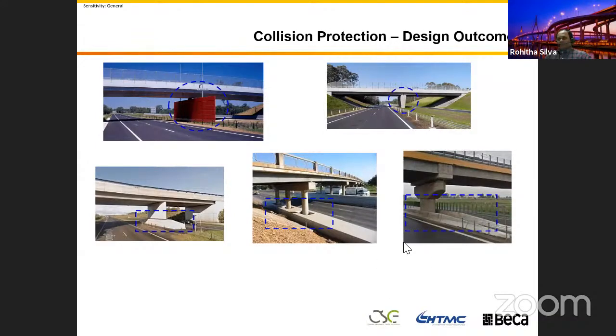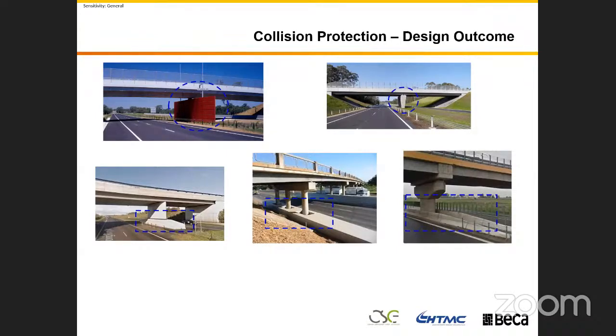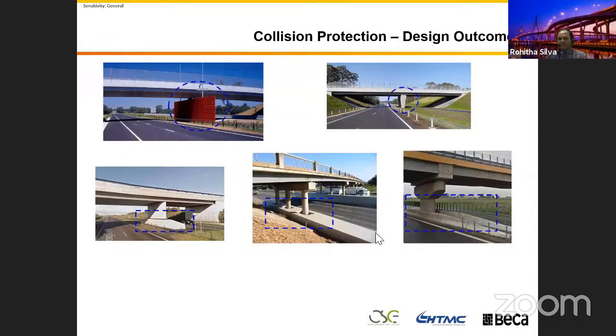Another thing, while you build a highway and open it, if you have to go back and rectify those things, it's not that easy. You have to work around an environment with people driving in either direction at least 80, 90 kilometers per hour. Working on concrete and reinforcement is not an easy fix, right? So construction takes a longer period of time to build. At least you need to wait 28 days to get your concrete strength.